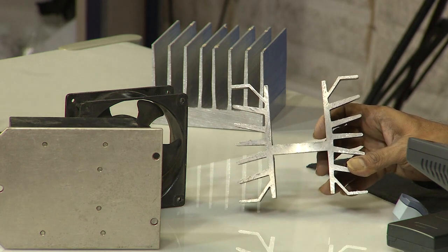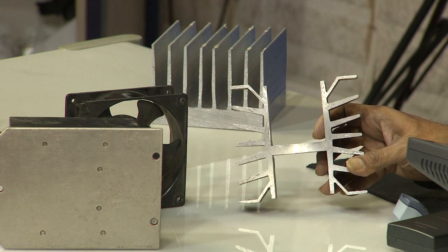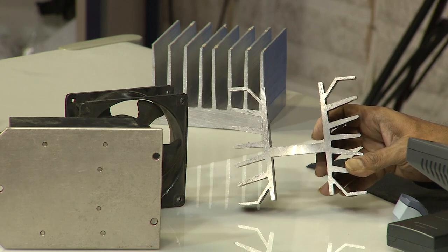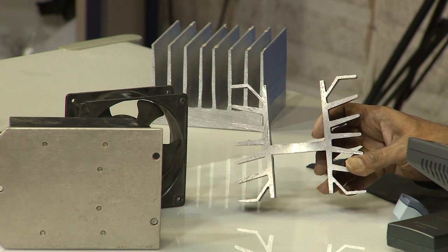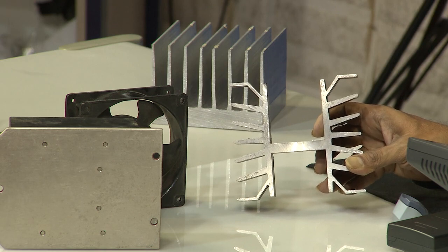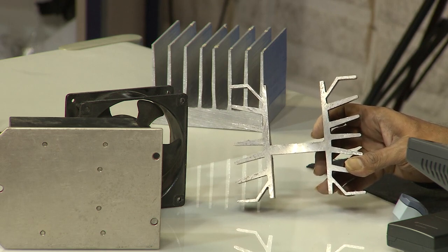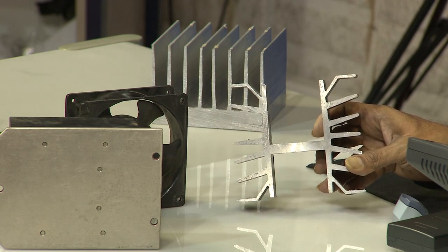Seen that, no? You seen the beautiful cross section. This was what I was trying to tell you, and you see the way the fins are tapered to improve the fin effectiveness. And then if you consider all the other things, saying I have a fan here and why not make it deeper and all that, the consideration about it being deeper or spacing, you have only so much control, not infinite control as you would have for an analytical thing.